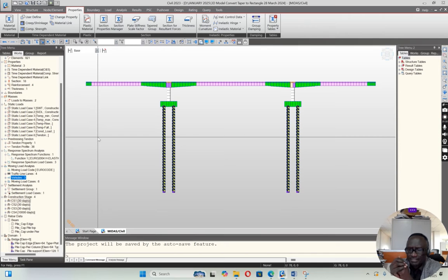Sometimes these girders are precast, so you have to find a way. You first precast. From there, you allow it to harden to maybe 90% of its 28-day compressive strength. Then you begin applying the cables or tendons. The tensioning sequences and final tension forces should balance with the compressive and tensile effects of the concrete. Because of that, the use of time and the sequence of your work are always taken care of.